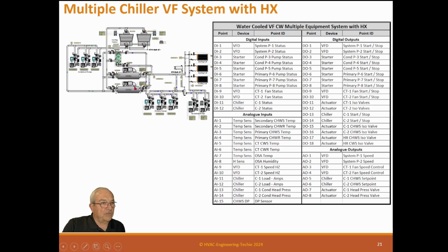These systems like this are generally set up so that one pump is dedicated to a chiller even though they're headered, and one is standby. And normally one tower is dedicated to a chiller, and this one's to this chiller, and no standby. But you can switch them, but normally that's not automatic. It needs to be a little bit more work to do that. The only reason is that it makes things so much simpler for operators. If they have a chiller fail, just switch your pump also. It's no big deal. When you try to say pump P1 is running chiller 2, it just gets confusing for operators. So I prefer them to be locked together in software. With a switch, you can change it, but it's just easier to tell what's going on that way.